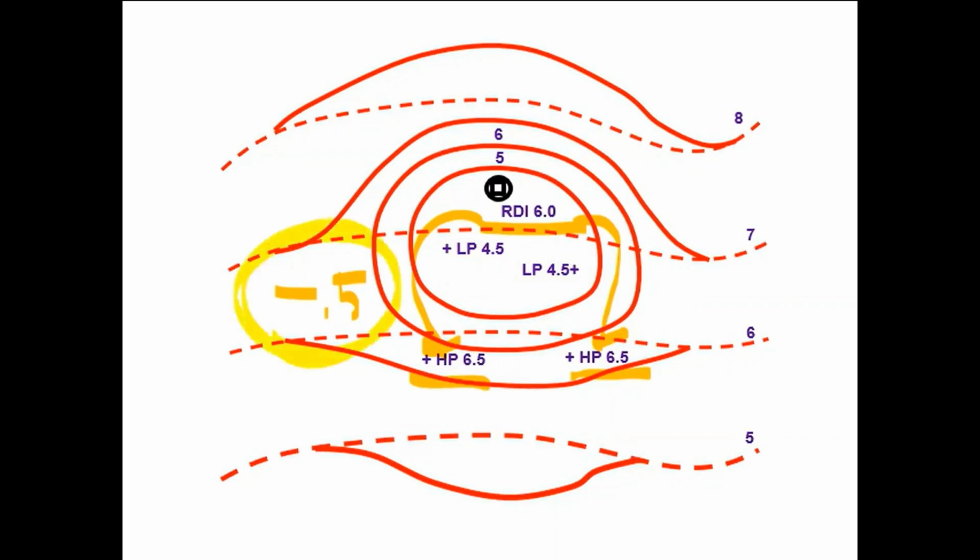The reason is that when these things are constructed, construction is not always perfectly accurate. And you want to make sure that your raised drop inlet is not just a tad below, but actually half a foot below the berm that you have shown on the downhill side.